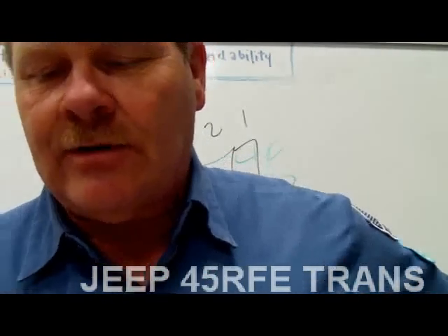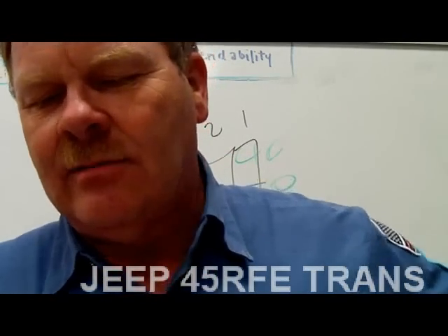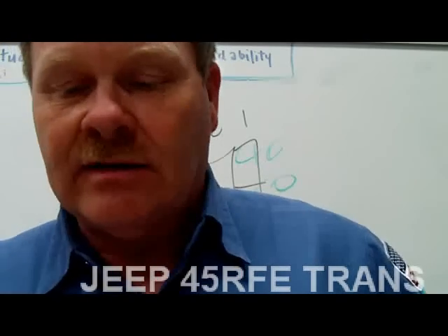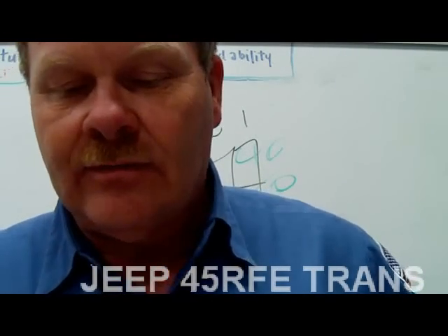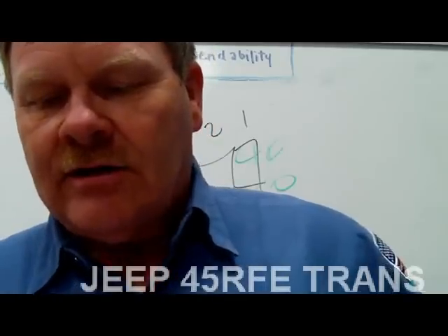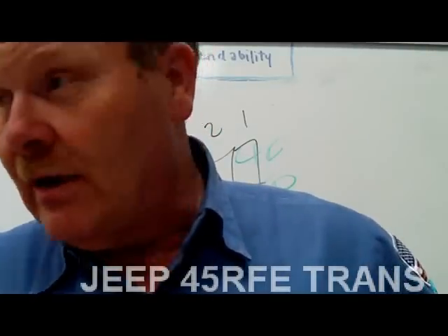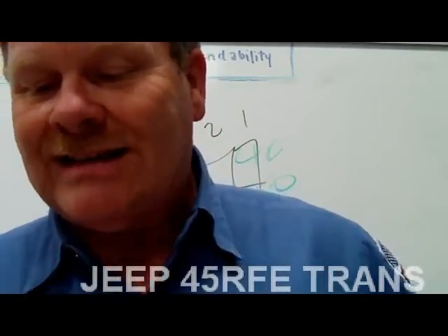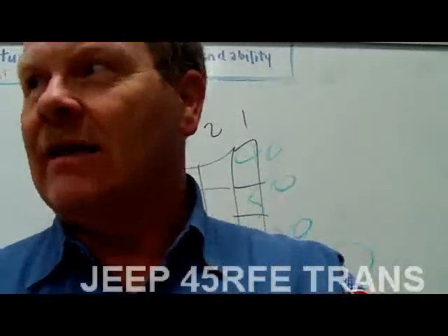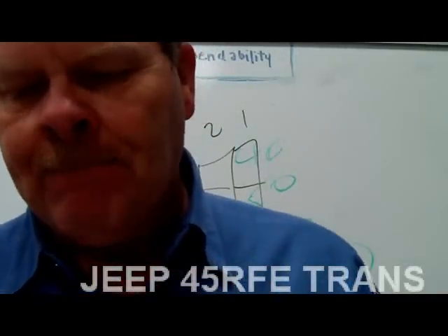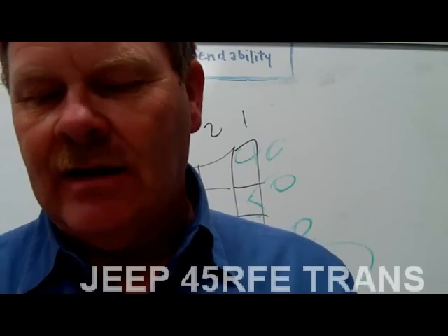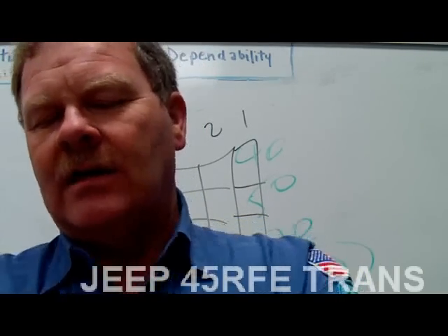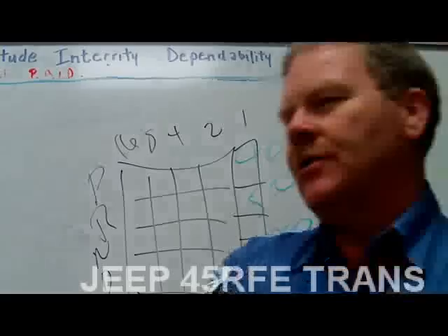The transmission temperature sensor is a thermistor that the TCM uses to monitor the temperature of the transmission fluid, because it has to have a different strategy for controlling the pressure whenever the fluid's cold. Okay, the solenoid pack, which is what you're talking about. This one is inside, up in the pan, not on the outside of the transmission. It's got switches that look at the hydraulic pressure in each clutch circuit. That's the feedback for the fluid pressure.